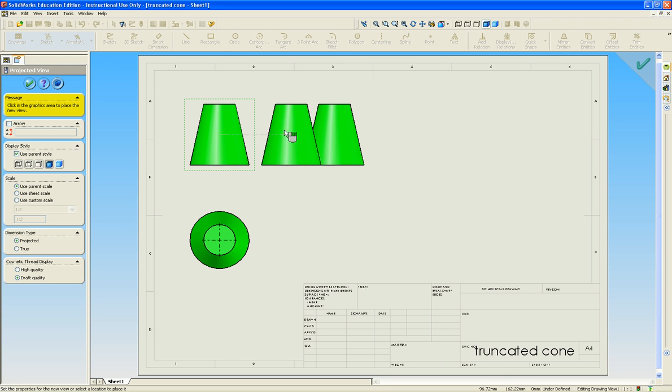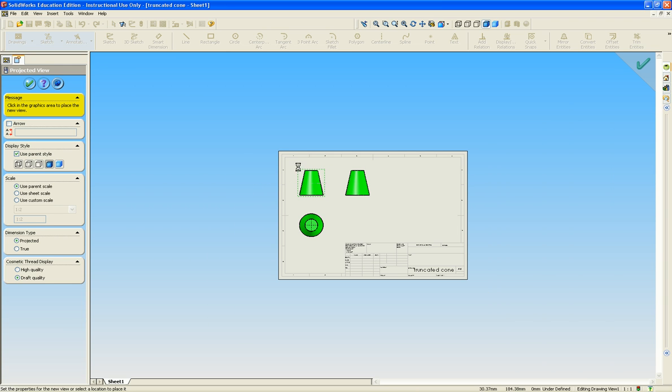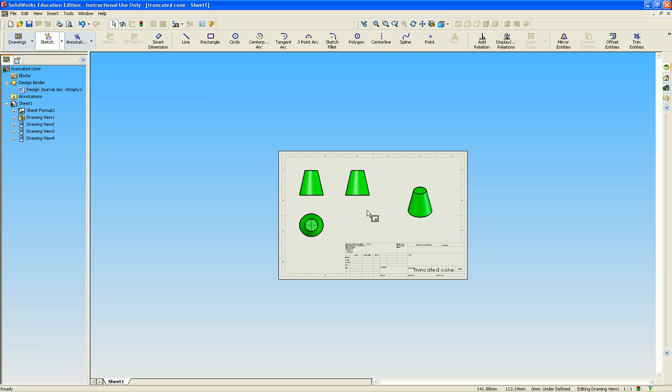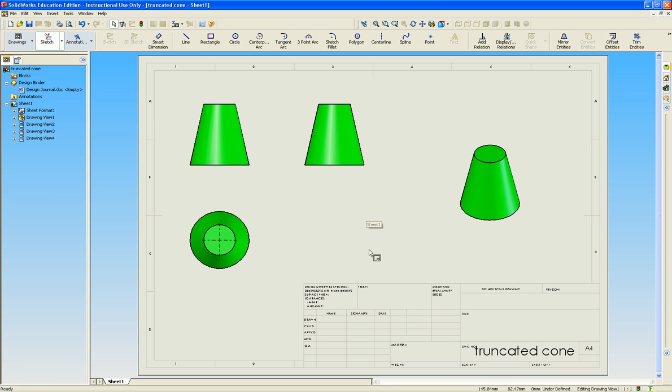Now to get an isometric of it, what we'll do is go out at 45 degrees from your elevation. Now scroll out a bit from it. Now what I want you to do then is hold down the control key on your keyboard, and you haven't clicked on the mouse yet at all, and move it into a position, and then just click to drop, and then just tick OK and you're done. So that's plan, elevation and end view done.